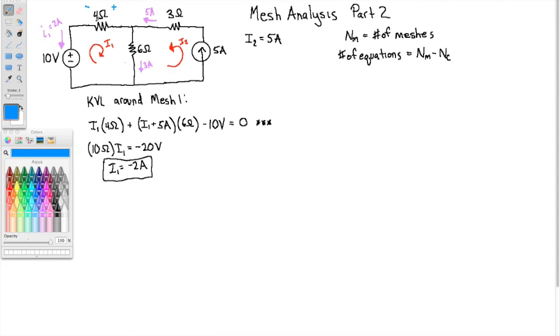And you know that the current through a resistor goes from high potential to low potential. That is, the marble always rolls down the ramp. Okay, so we know that the right is going to be the higher potential, the left is going to be the lower potential. What is that voltage? Well, we've got 2 amps and we've got 4 ohms. So Ohm's law says that that is 8 volts across.